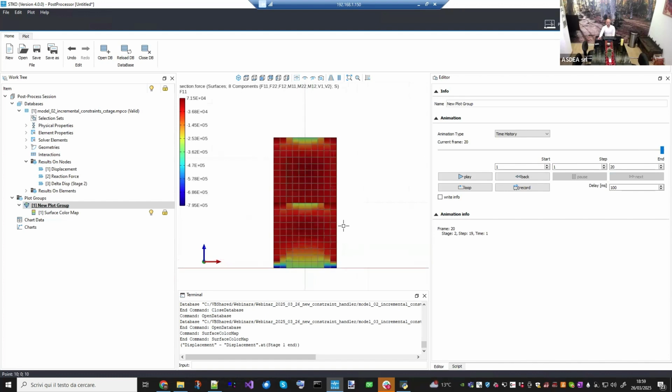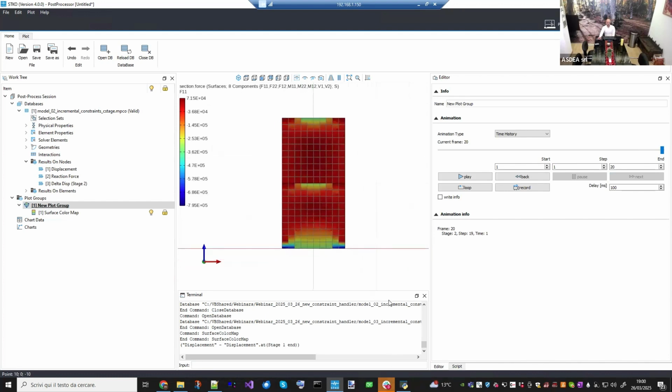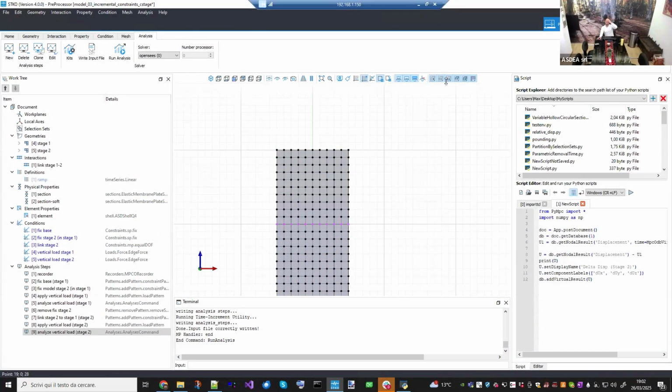And yes, with this one, I finished this webinar. And now if you have any question, we have some more minutes. But the idea with this webinar is that I've seen that many users, when they have problems with instabilities with their model, most of the time it is due to constraints. Sometimes they forget to assign certain constraints, so the model is singular.